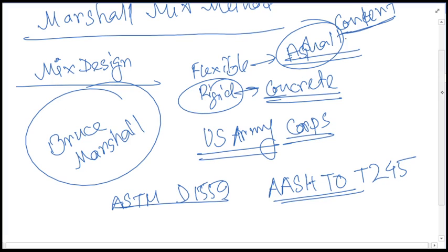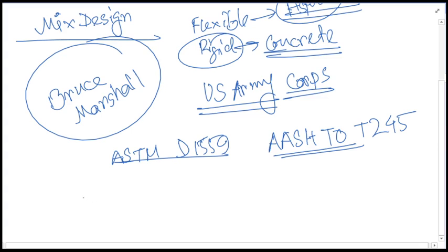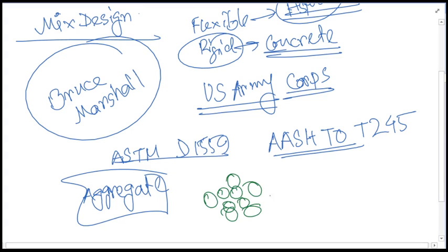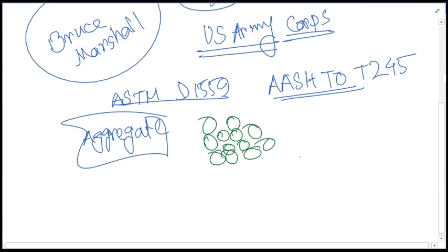So what is our main purpose here? We will have a particular amount of aggregate. So we will have a particular aggregate sample. Using that aggregate sample, we have learned throughout the sessional of this course different properties, flakiness, angularity, and different properties as well. After validating all of the properties of those aggregates, finally we'll be choosing one aggregate for our mix design. And for this mix design with this aggregate, the amount of asphalt content which will be